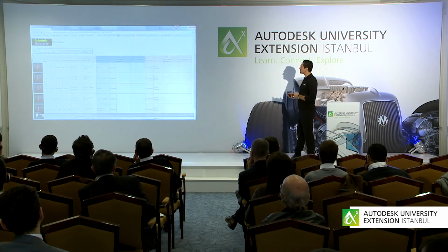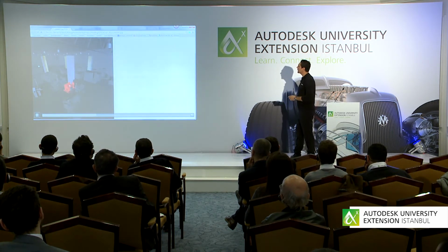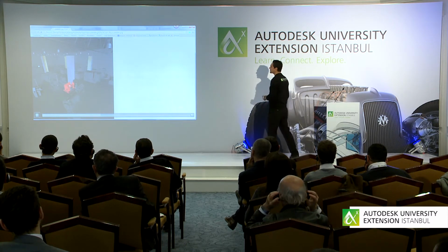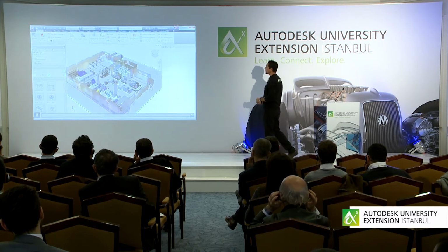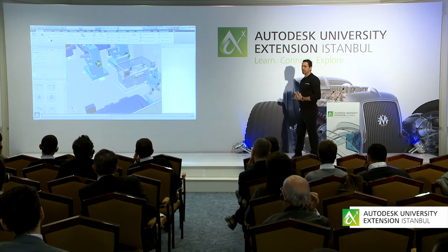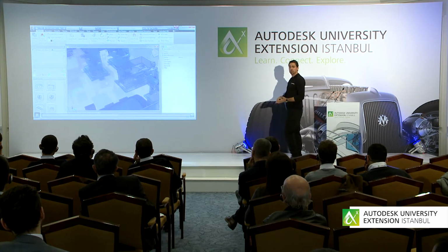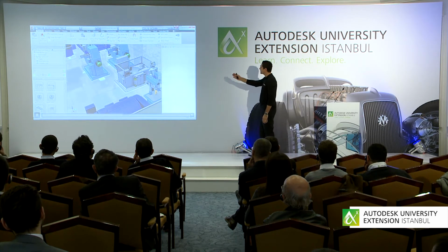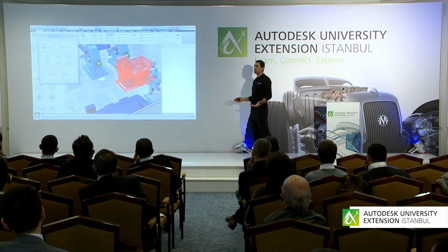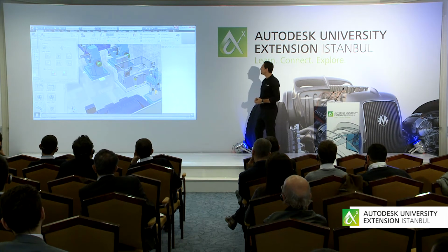That report gets translated into an HTML file and some pictures and so on, highlighting where these clashes are. Gives the designer the opportunity to go back into the actual model, whether it's 3D or 2D, and shift, move, or amend what the situation has come up to be.